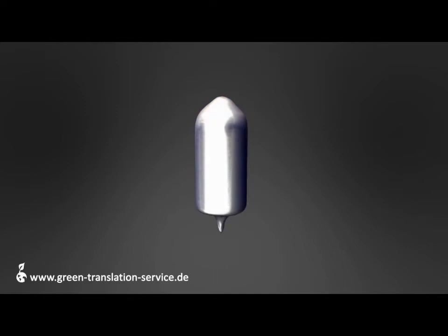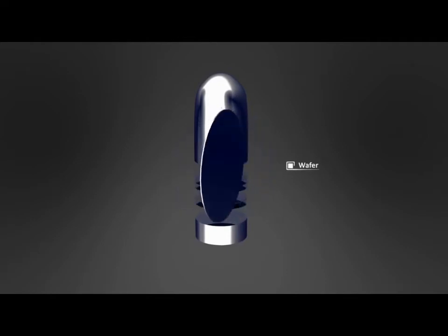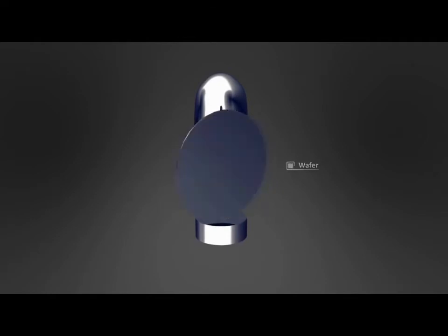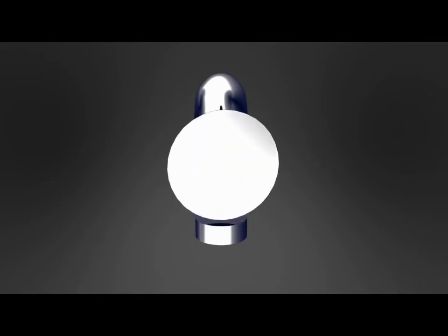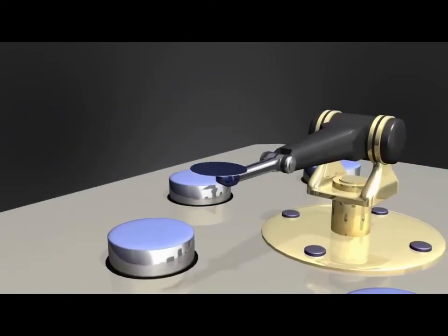The block is cut into wafers of the desired thickness of anywhere from 0.5 to 1.5 millimeters, depending on their intended use. The wafer is then polished and subject to rigorous inspection. If the wafer passes the subsequent inspection, the first step of production begins, which is called front end of line. Here, the integration of transistors takes place.